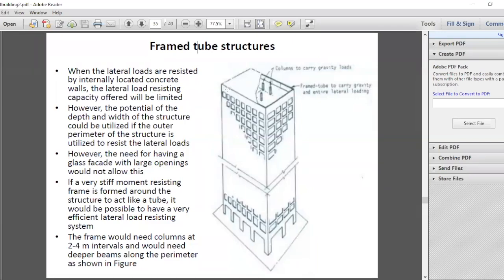Then what you find is, although we expect the stress in the flange to be equal everywhere, the flange deforms more at the web, it deforms less away. So you will find the stresses are different. That means the full flange cannot participate in resisting the moments. So this is called shear lag.